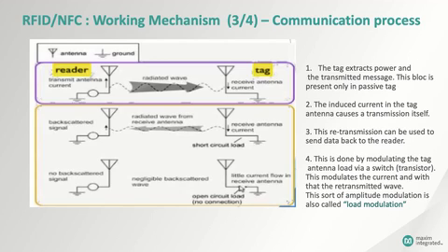When the tag presents a high impedance to the receiving antenna, the current path is removed. That's shown in the third illustration. In the transmitter circuit, due to mutual inductive coupling, there's a similar reduction in current. Now, in this way, the tag can vary the impedance in the receiver's antenna circuit, causing a change in the current flow in the antenna circuit of the transmitter, and that's how the tag gets data back to the reader.